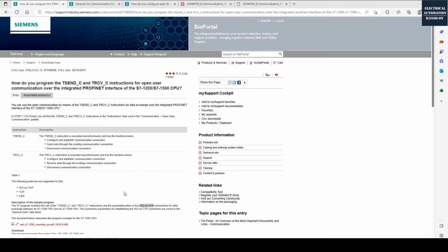So basically, if you are using a Siemens CPU to communicate with another Siemens CPU, for example, an S7-1200 or S7-1500 PLC, where they are all Siemens PLCs communicating with each other, I highly recommend you use ISO on TCP. A common case is when one Siemens PLC CPU needs to communicate with other devices, for example, sensors or cameras.